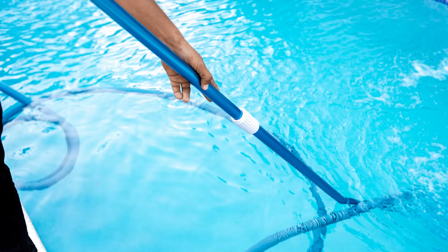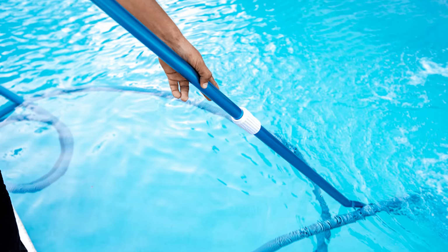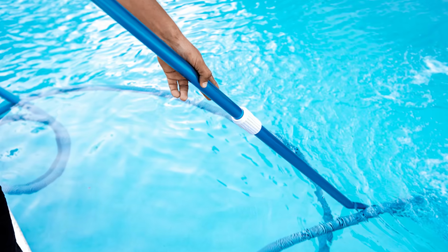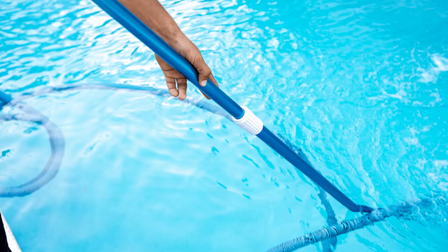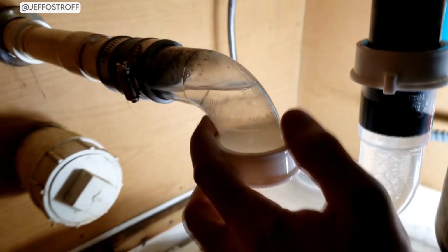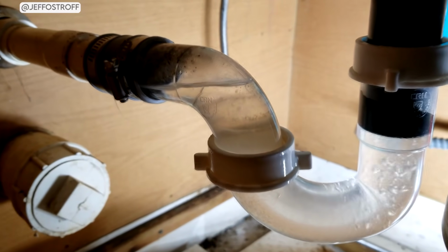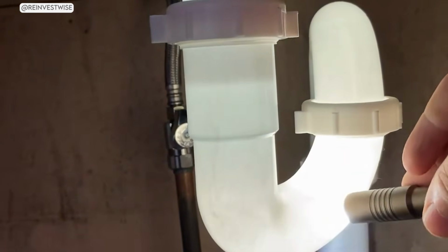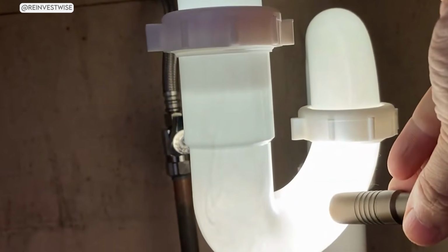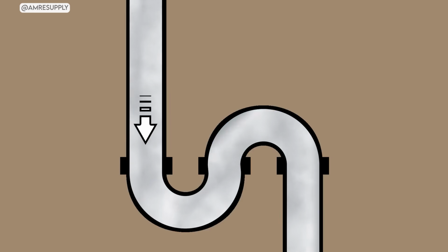This is the exact same principle that makes a siphon work when you use a hose to drain a fish tank or siphon gas out of a tank. Once that column of water gets moving, it does not just drain the water you sent down the sink. It keeps pulling. And what it pulls out is the trap seal. That critical 2 inches of water sitting in the bottom of the curve that is supposed to protect you.